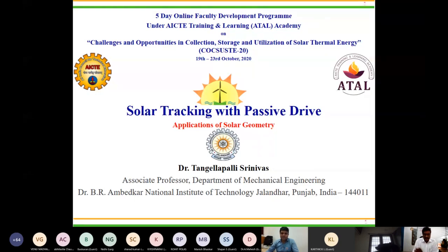The collection may be non-focusing or focusing type. Even non-focusing, that is a flat plate collector, needs some intermittent change of the tilt angle so that we can receive the maximum amount of solar radiation from the sun, so that we can expect higher thermal efficiency, the energy conversion efficiency from the thermal system.